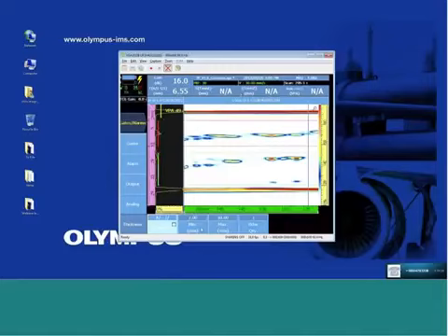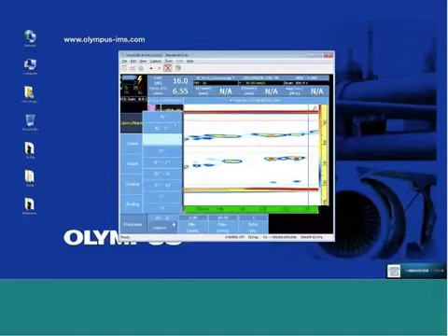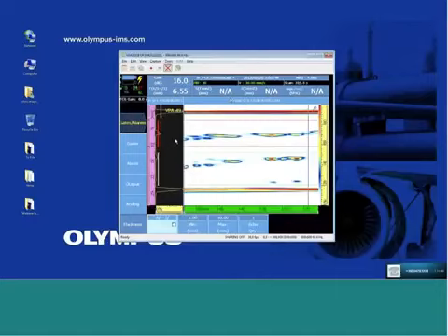And again, both of these, including the source of the reading, can be adjusted anytime after the inspection since we're saving the full A-scan. And again, in the A-I, the 655 is a result of the leading edge of gate A here subtracted from the leading edge of gate I here.